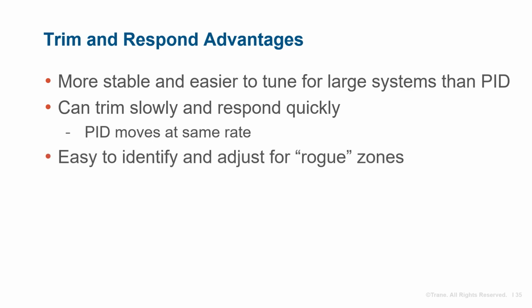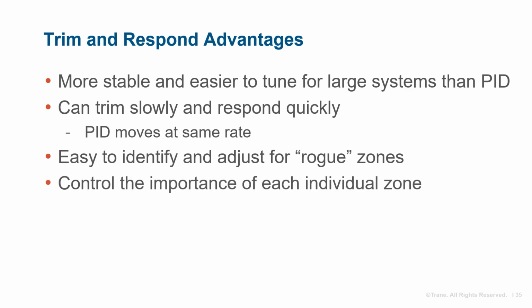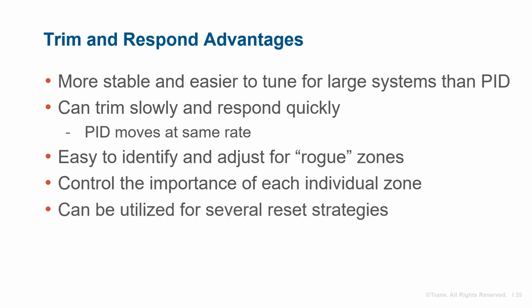Since the system is receiving requests from each zone, those that may be having mechanical or maintenance issues are easy to identify. Trim and respond also adjust the importance of individual zones and may be used for many optimization strategies in both airside and waterside systems.